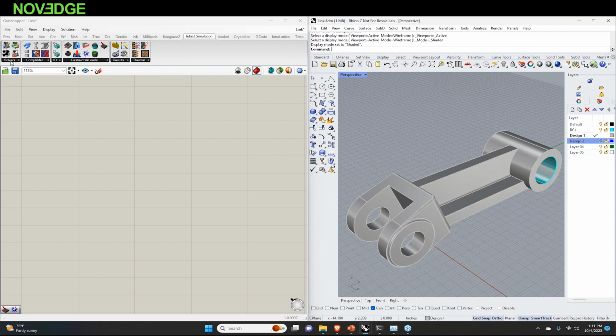Here we see our solvers. We've got a variety of solvers available. We have components and materials, restraints and loads for structural problems, as well as boundary conditions for thermal simulations. Then we'll get into the results and the other I/O things as we go along. So to set up a stress simulation, we choose the stress simulation block and add it to the canvas. Now, working top to bottom, we specify solver settings, components, restraints, loads, surface loads, and volumetric loads.